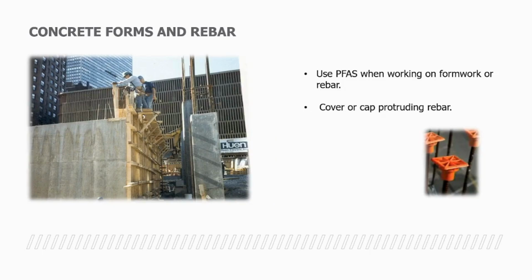Concrete forms and rebar. Use personal fall arrest systems when working on formwork or rebar, and cover or cap protruding rebar. If you look at the picture over here to the very far right of the screen, these are what they call rebar caps. This particular one is kind of a square looking shape. There's different colors, there's different sizes. Different companies make a variety of different ones. But when it all comes down to it, if you work around any type of rebar that's going to be protruding upward, it shall be guarded. Okay? Have a cap put on it.